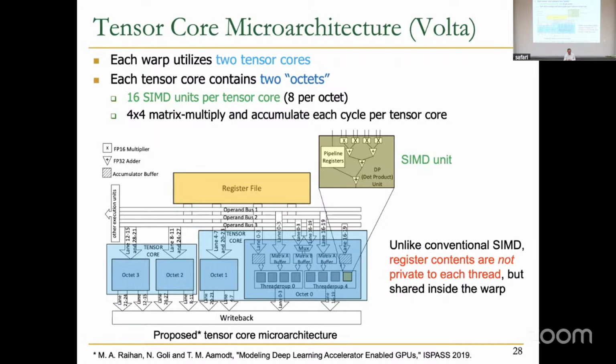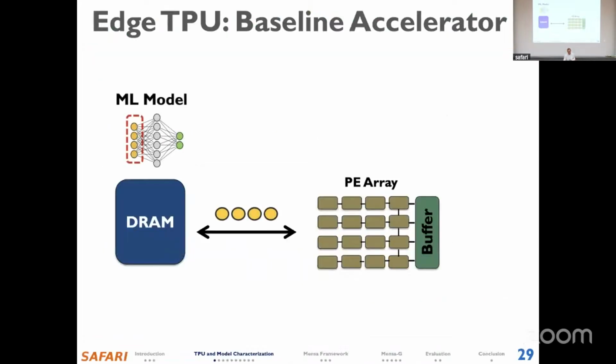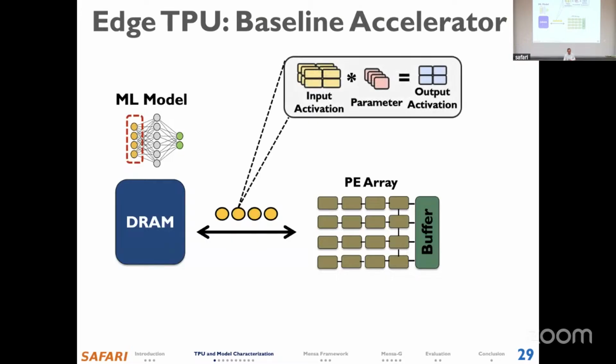So these tensor cores are actually kind of competitors to systolic arrays. I will not go through the systolic arrays again, but this is Google's Edge TPU. It has systolic array processing elements over here, and its goal is essentially to do matrix multiplication also. We've seen an example of this when we covered systolic arrays, so if you're interested, you can take a look at it.